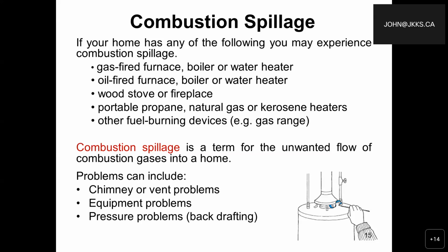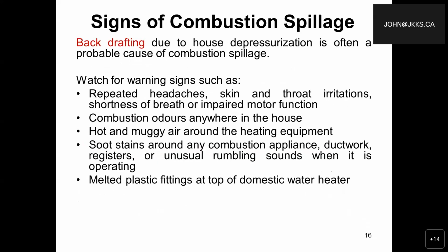We can see here where they're depicting a smoke pencil being used to see if it actually is going up the chimney or perhaps coming back towards us. So again, just used as an example here. What are some of the signs of combustion spillage? Well, backdrafting due to house depressurization is often the probable cause of combustion spillage.